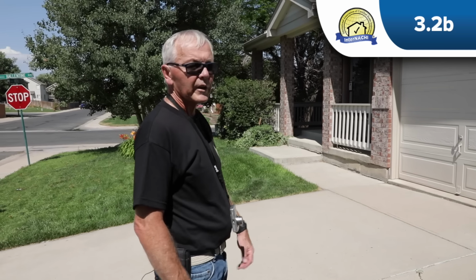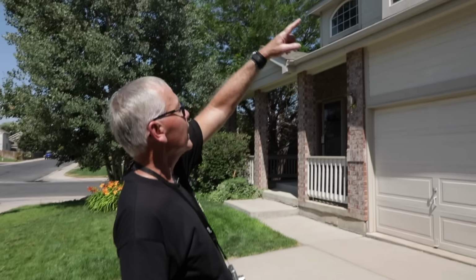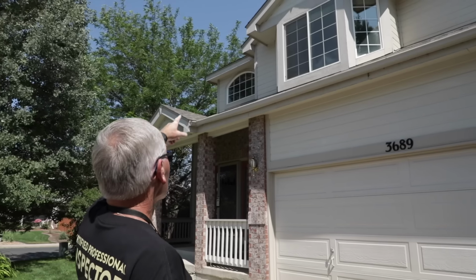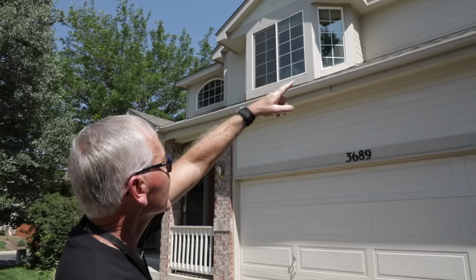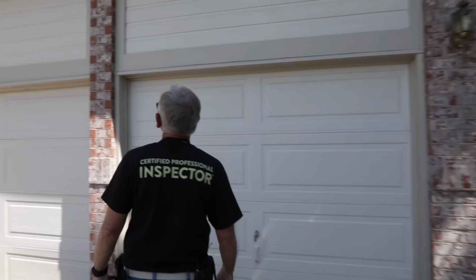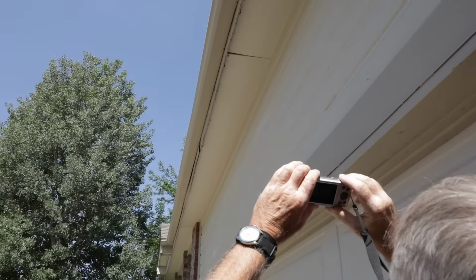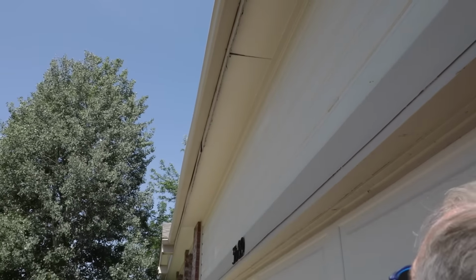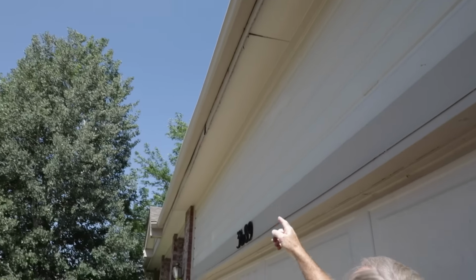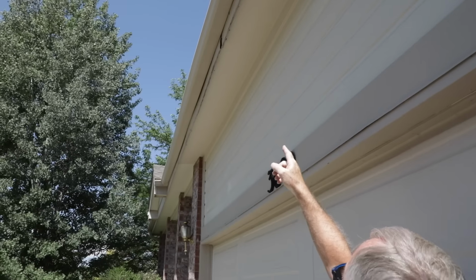This is the exterior eaves, soffits, and fascia. So we're going to start up here in the front of the house, and I'll start looking at everything up above on the second floor. Okay, I'm going to move down to the next level. I get down here, I can see some loose soffit right here. I want to note that. And as I go down on this fascia, I've got some water damage right here too, and it's loose as well.